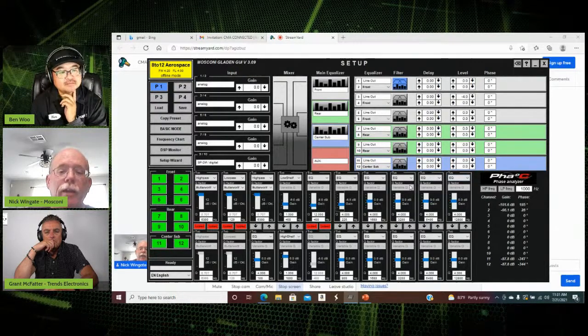That's the reason why this is here, because you can turn so much down that you can get yourself a flat line. Before we do any delay work and before we set any levels, you've got to make sure that all of the speakers are playing at the exact same level, plus or minus about 2 dB.